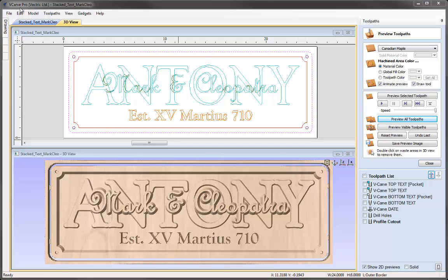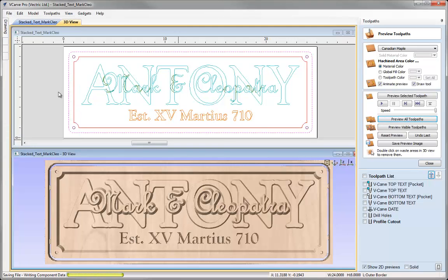So to finish off, let's save this. So file save, overwrite the one that we saved separately there from our template, and we've pretty much completed this example. We've looked at some interesting things in here though. First of all, we went through quite a detailed setup of our original part to create the template. To do that, we were very diligent about our use of layers and how we organised them and named them. We created specific layers for data that we didn't want to actually toolpath, so that was the first name and last name in this case, because we needed to do subsequent operations on it to weld it together that would have made it very difficult to edit.